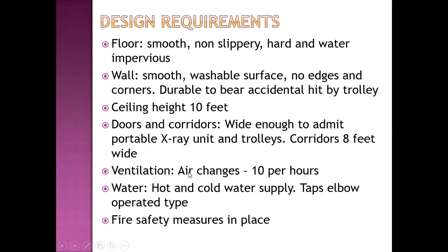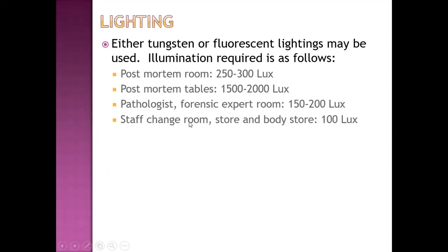There should be proper ventilation with 10 changes of air per hour. There should be availability of hot and cold water, and tap should be elbow operated type, and there should be availability of fire safety measures. Either tungsten or fluorescent lighting may be used.